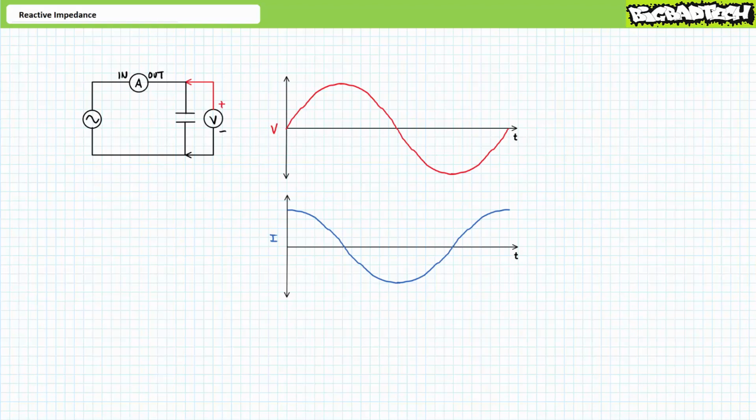This is essentially the same reason capacitors exhibit a phase shift between voltage and current in AC systems. During the charge phase, current rushes into the capacitor and capacitor voltage rises. During a subsequent discharge phase, current rushes out of the capacitor and capacitor voltage drops. The problem in identifying the present state of a capacitor in AC systems is that the polarity cyclically oscillates at a frequency too fast to allow a technician to change the leads of a voltmeter or ammeter to adequately reflect the actual state and polarity of the capacitor.